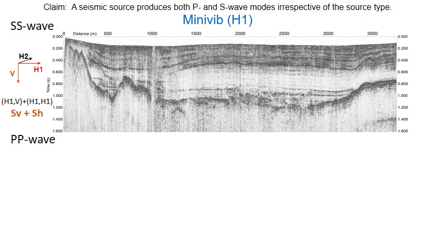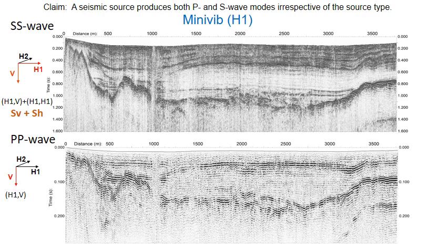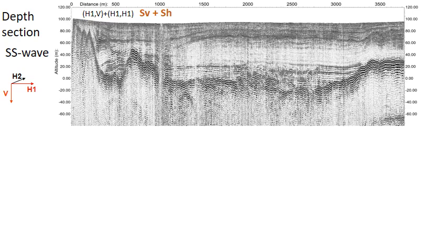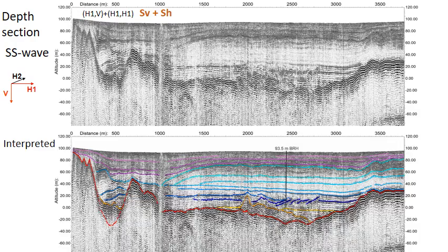This shear wave section has been shifted to a datum using the surface topography, and we can compare it with a P-wave section extracted from the same data set using the vertical receiver component only. Here again, we can see how much better resolution we can get with shear wave data. This section has then been converted to depth and interpreted for locating an appropriate spot for drilling a borehole.